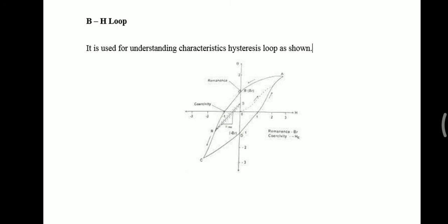In the curve OA, if the sample is subjected to a magnetic field, then B and H in the magnet follow the curve OA as the external ampere turns are increased. Curve AB: if the external ampere turns are switched off, the magnet relaxes along AB.